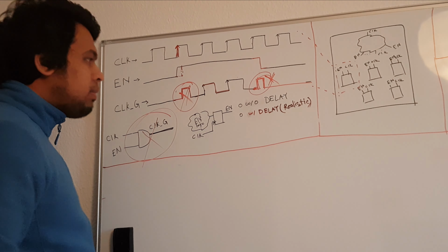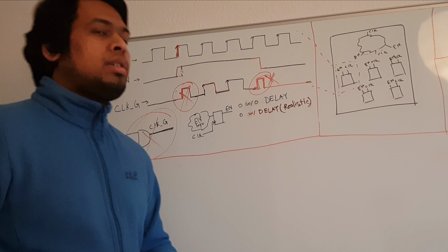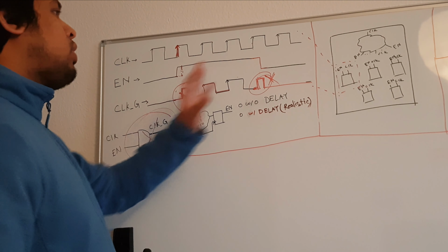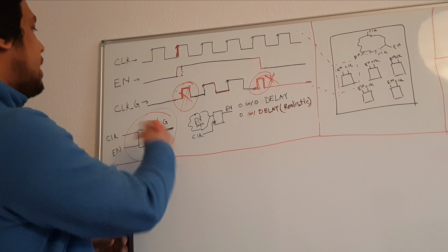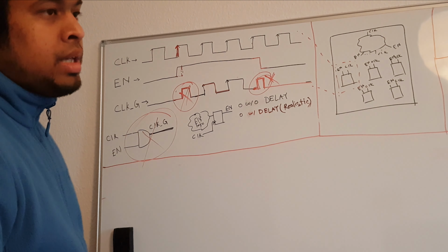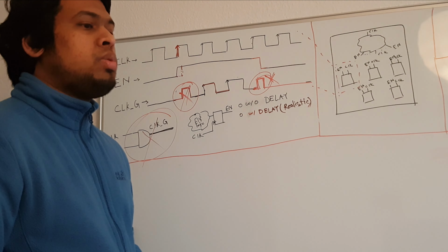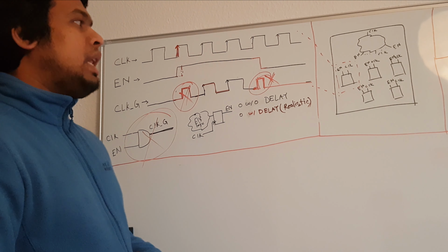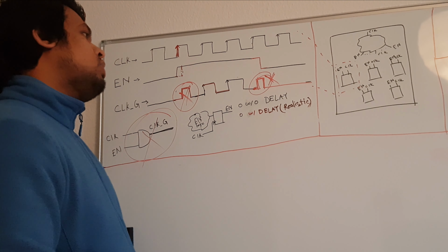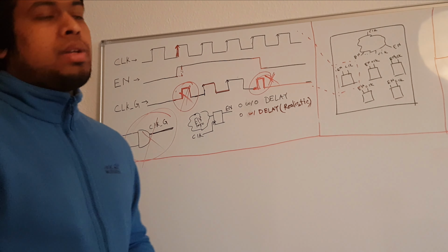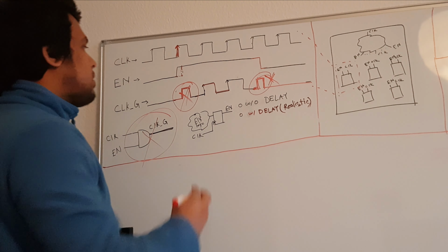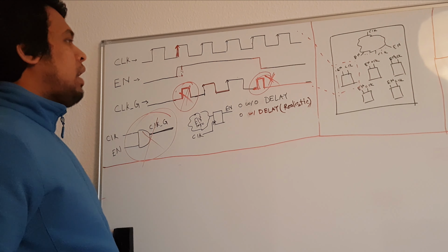And probably when you are doing the front-end design and you have designed this, and your design has been transferred to your colleagues who are doing the place and route and layout, they will have some serious problems doing the clock synthesis, because they will have problems with the glitch and with this duty cycle.